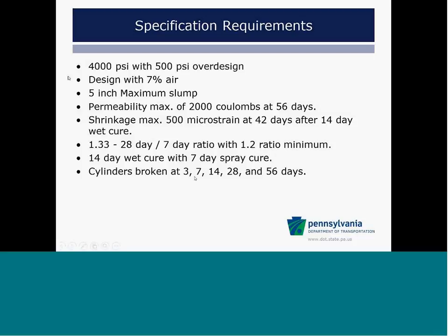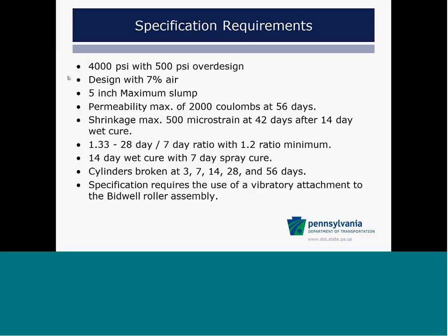Cylinders, we're going to break cylinders at 3, 7, 14, 28, and 56 days. This is to gather data. Thinking about some things as far as 56 days. The specification requires the use of a vibratory attachment Bidwell roller assembly. This is to get a better finished surface so that we don't have to finish it. Hopefully we don't have to touch the surface after the Bidwell, or as little as possible.